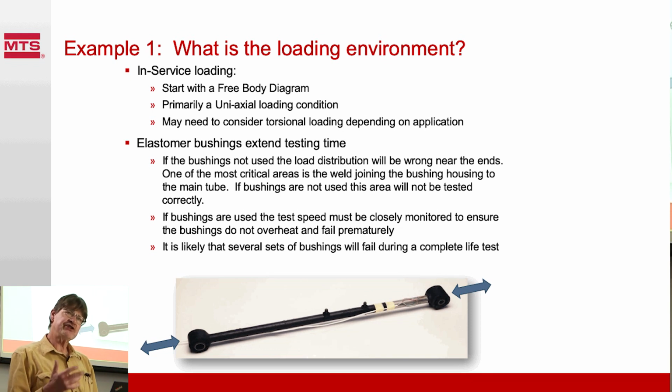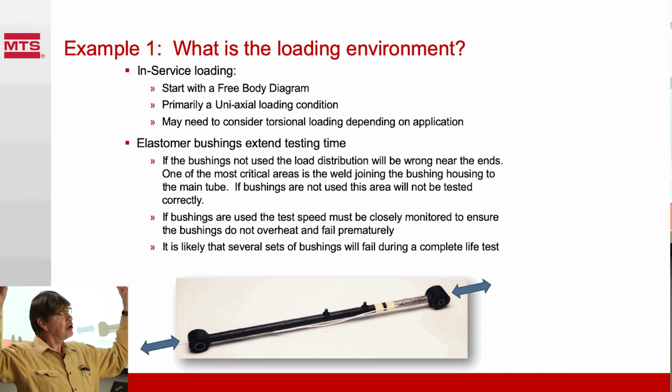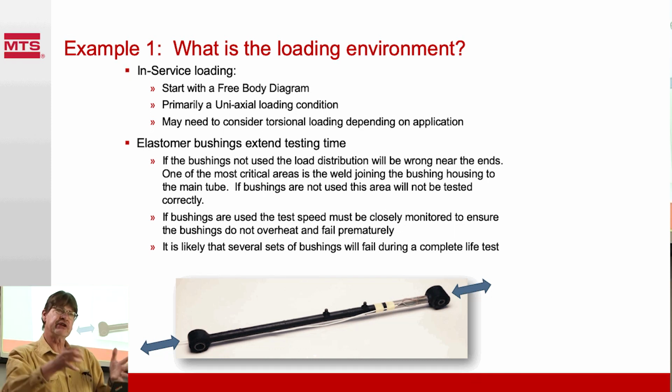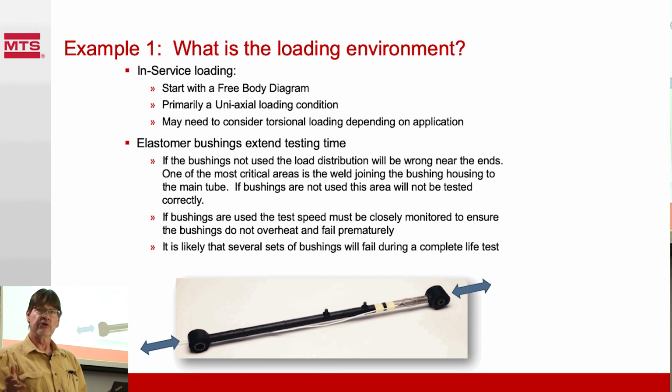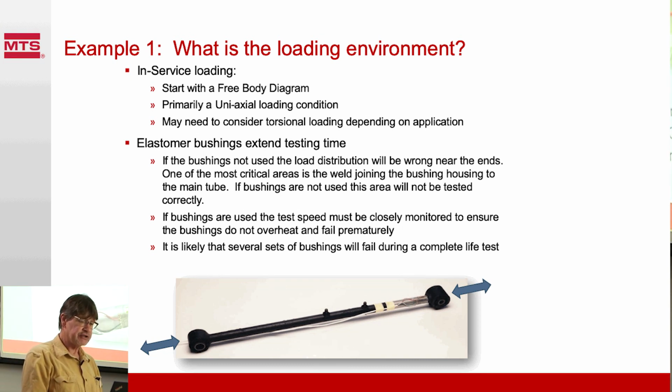So we need to make that decision. What's the objective of the test? Again, what are we trying to do? What do we want to learn from this test? Do we want to learn the fatigue of the welds? Do we want to learn the fatigue of the stuff welded to it? Those are two different requirements, and really we could operate those as two different types of tests.